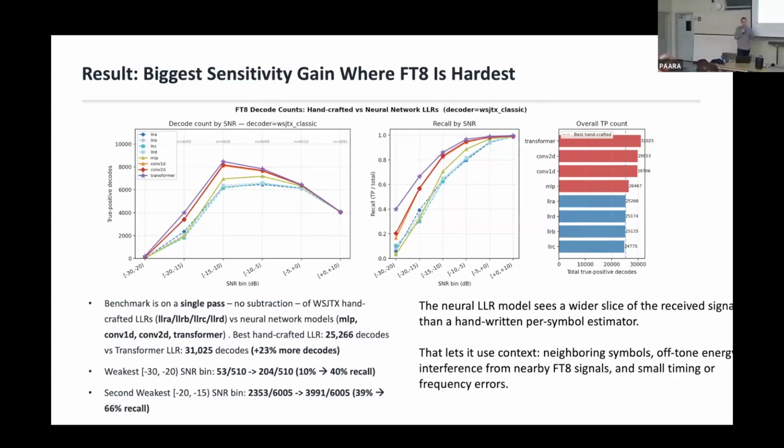Technically I've said FT8 is FSK, but they have a little modification: the phase doesn't just jump when you change between tones. They keep the phase continuous, and because of that, knowing one symbol gives you a little bit of information about the neighboring symbol behind it. It's kind of an inside baseball thing.